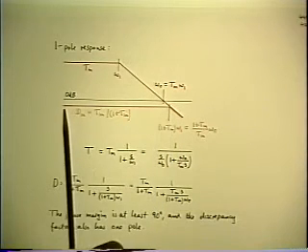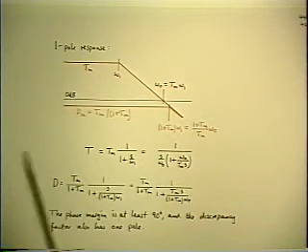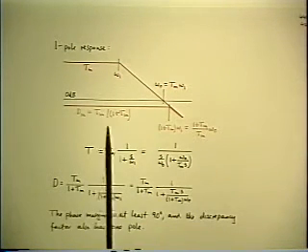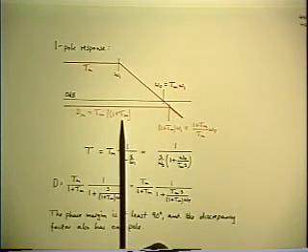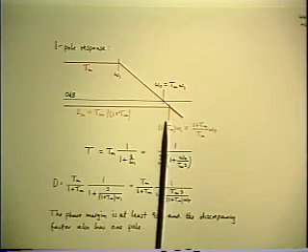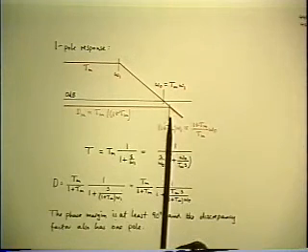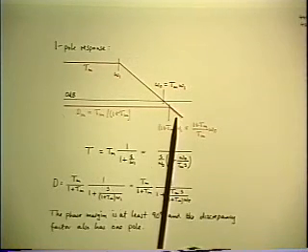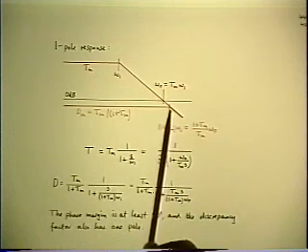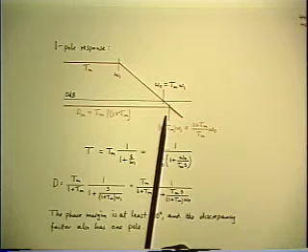And the next step is you multiply the D by the G infinity to get the closed loop gain. Well, we don't need to go through that step anymore at the moment because it's the shape of D that is going to determine that result. And the objective is to get D as close to 1 as you can, which you do by making the loop gain large. However, you still have to account for the fact that it's going to go away eventually. So the closed loop gain that you get for this case is a flat value and a single pole, which of course actually has a 3 dB smooth corner.